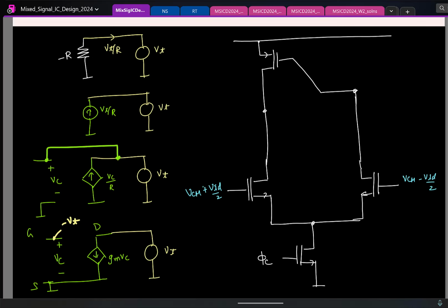Logic clear? Okay. This point is okay, right? So we are trying to replace this VCCS with a transistor. So we are choosing a PMOS because source has to be incrementally grounded and source is at VDD. Now to get this negative resistance, if the drain is at a potential VT, gate must be connected to negative of the drain. Fine? Okay.